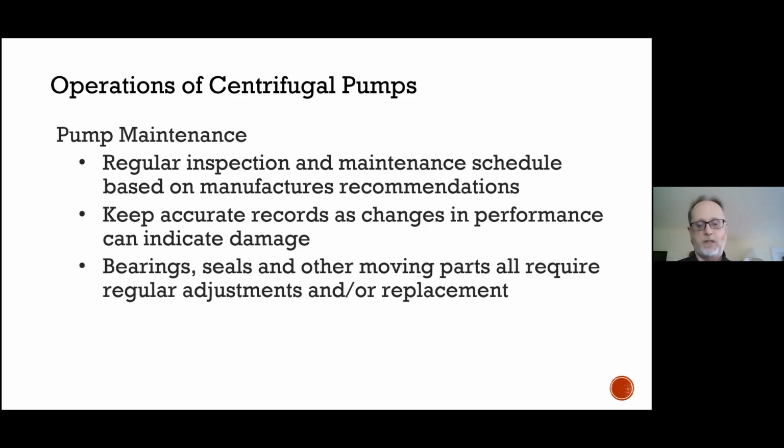For instance, on March 24th, 2020, a pump cycle was 20 minutes, and this year it's 25 minutes. Well, that might suggest where? Inside the impeller or the casing. So we have to keep accurate records, but they should always be based on what the manufacturer wants.